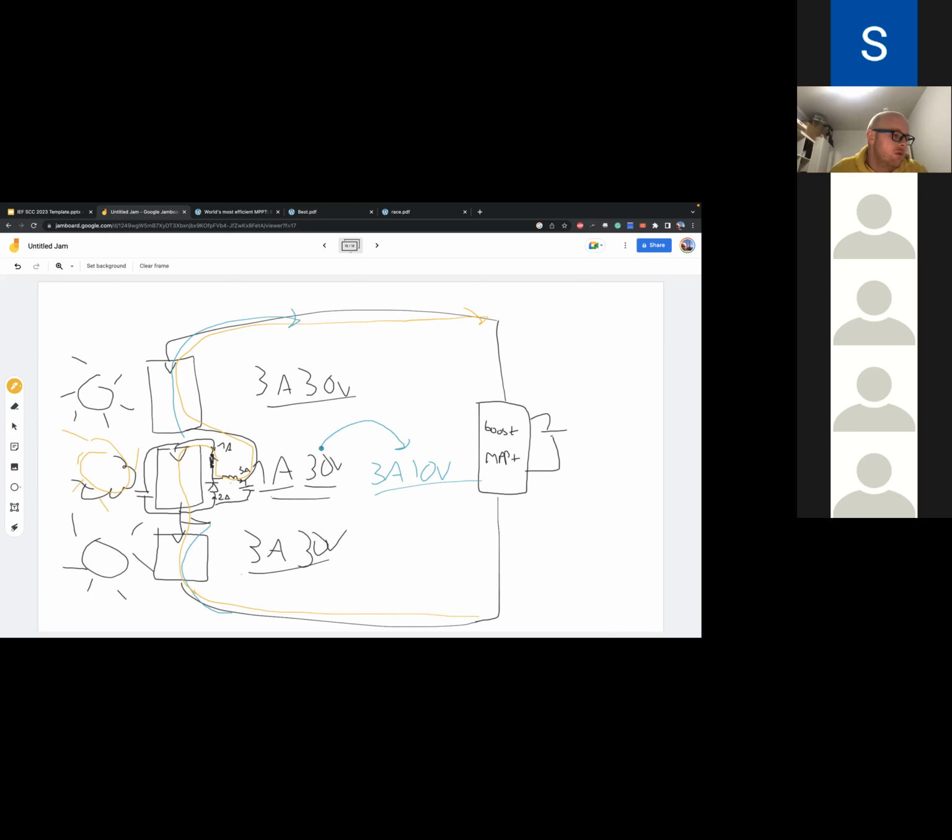Okay, that's interesting. They have these solar arrays, and they kept 1 string on the length or the vertical. I don't know what they do. I think they do 6 or 4. They make a little cluster. And Taylor Solar, they're doing it on actual residential solar arrays, and they are just replacing the diode box on a solar array, with 3 or 4 diodes, by 3 or 4 buck converters. And they are doing this to increase the lifetime of the solar arrays and to reduce the heat hotspots in the diode box.